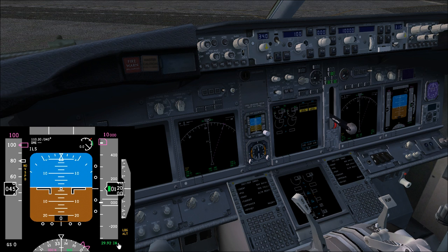We have down here the barometric set. This barometric now is in inches, but we can pass it into hectopascal, and I later will show you how to do that. Last thing, we have a landing altitude indicator here. The landing altitude indicator shows that we have not yet set the landing altitude into the pressurization panel. This can be done automatically by the FMS while selecting an arrival airport, or done manually by using the pressurization panel.